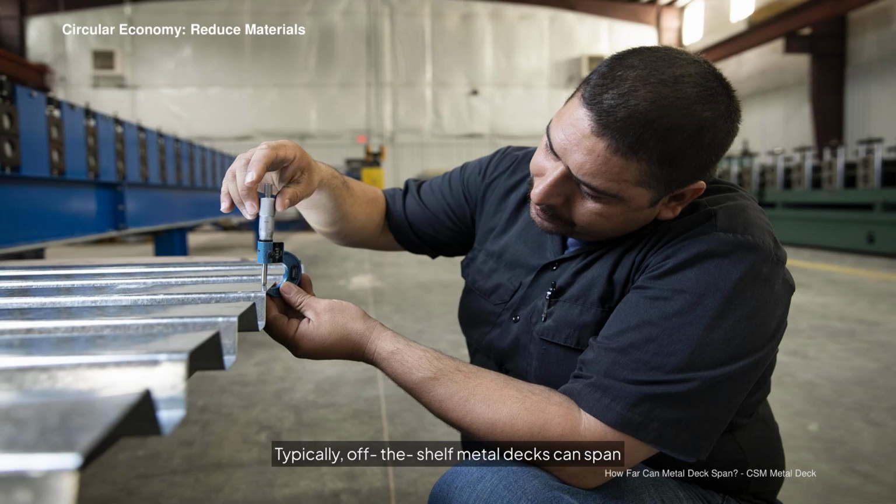Typically, off-the-shelf metal decks can span on the order of a few feet up to around 10 feet or a bit more between beams, depending on the type and gauge. For instance, a 3 composite metal deck in a thicker gauge might span about 10 feet without support. If the same deck tries to span 8 feet apart, you may be adding more steel members than necessary because the span underutilizes the deck's capability.